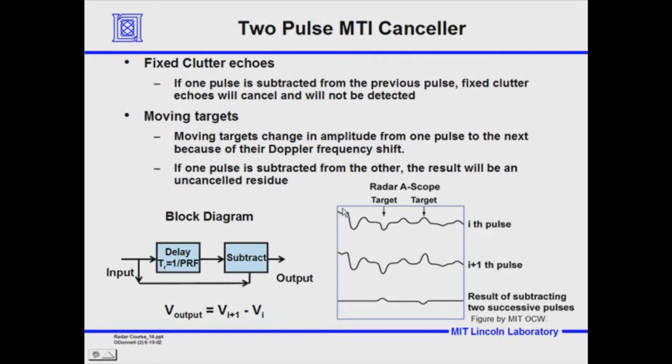Now let's look at that schematically first. Then we'll look over here at how one implements it. And here is an analog echo return from a radar. You can see that here the echo is from the ith pulse. We could call that the 6th pulse and this the 7th pulse. If this is the 6th pulse, that's exactly the same, so that'll cancel out. But over here, the echo is a little bit different than right down here when we send a pulse out right afterwards.